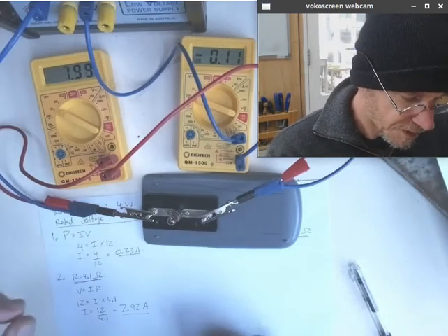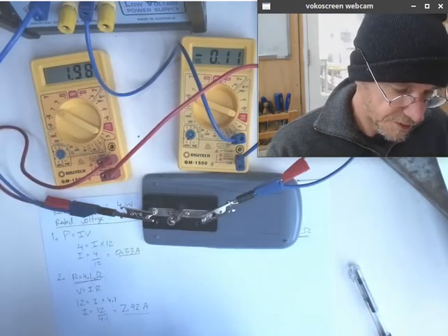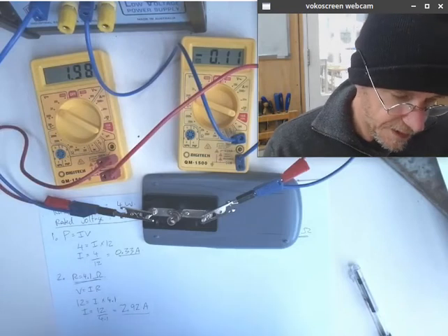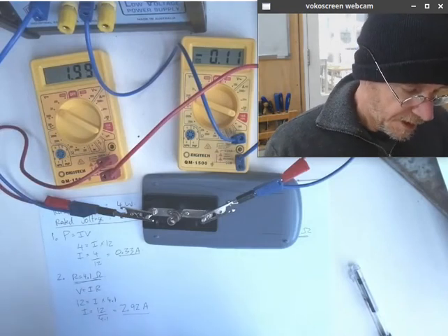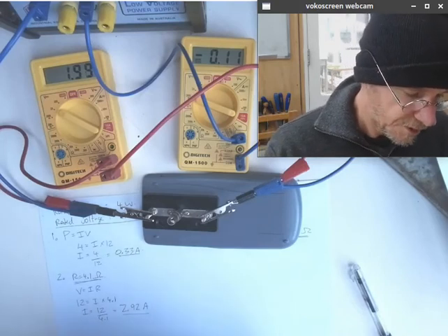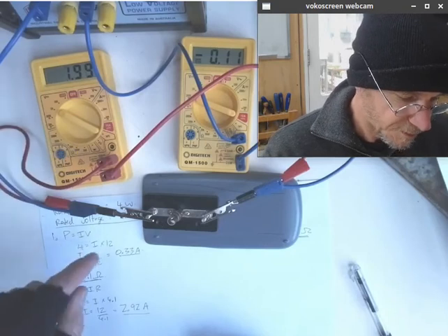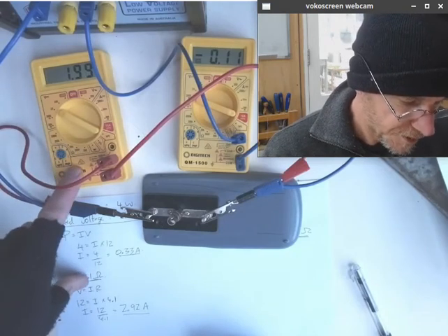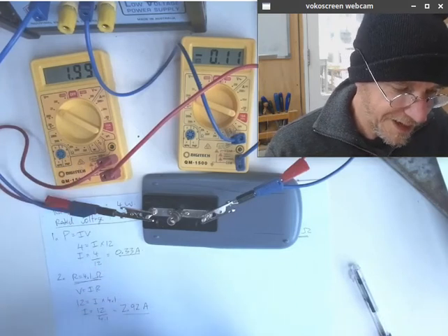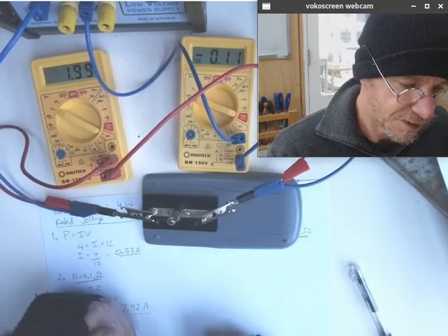you can't rely on measuring resistance with your meter if the product is either going to have a high inductance or is going to change temperature dramatically. In those circumstances, the resistance measured with your meter is not going to be representative of the resistance of the product, or the impedance of the product, in its use in the circuits in which it's going to be used.